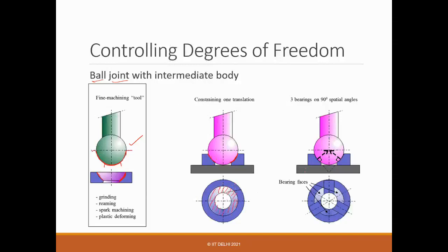So what you need is maybe just 3-point contact. So what do you go for? Three surfaces, three bearing surfaces, right? And okay, it can be spherical, but I think slowly you may realize that you may not need any spherical surface as well. It can be simply flat also. So just three flats from three sides, right?